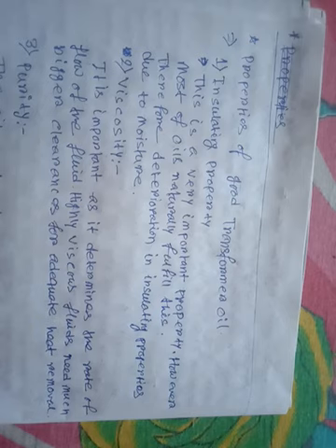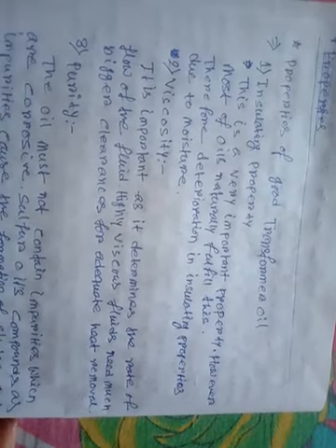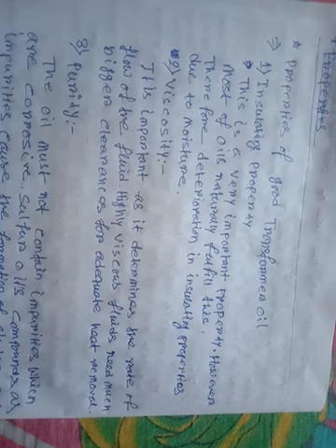Number one is the insulating property. This is a very important property. However, most oil naturally fulfills this. Therefore, there is deterioration in insulating property due to moisture. Second is viscosity. It is important as it determines the flow rate of the fluid. A highly viscous fluid needs a much bigger clearance for adequate heat removal.